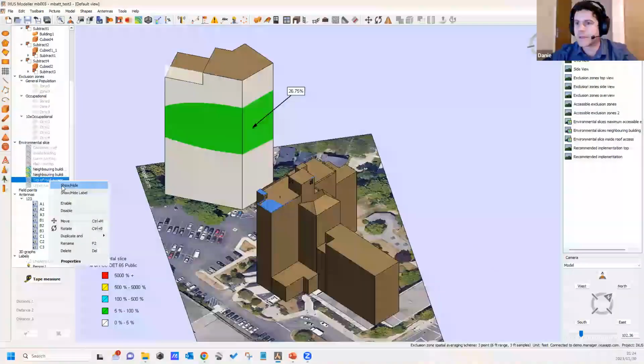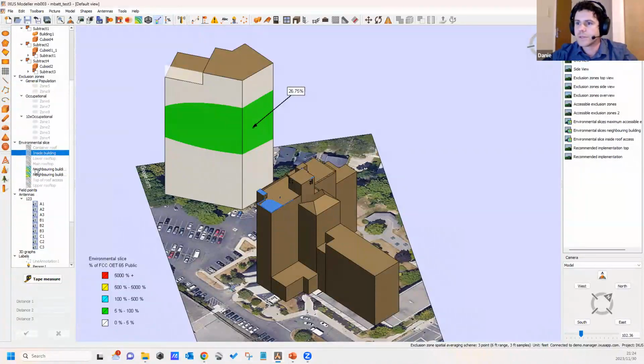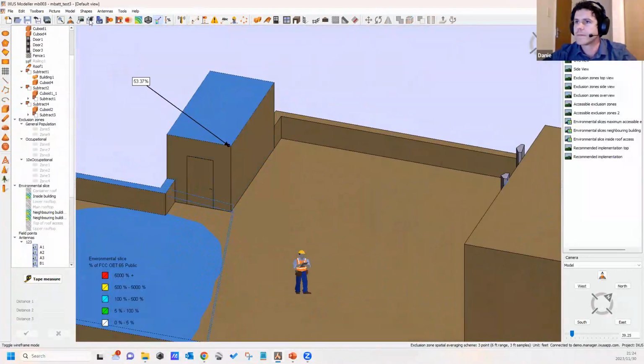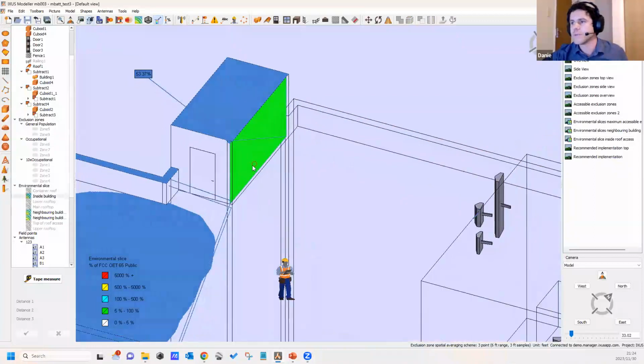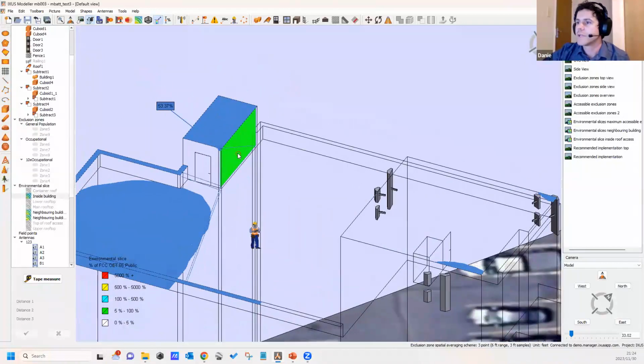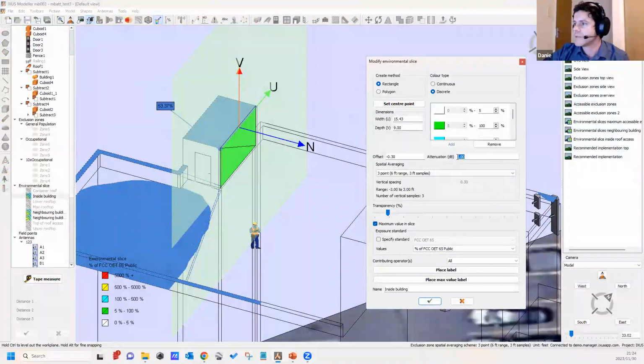as well as the inside of that building, which is over here. So as I mentioned, we can also use a vertical slice to determine the maximum of any area over here, and we can apply a, let's say, 6 dB attenuation to take into account the attenuation through that concrete, and then we can establish that that is also below the standard.